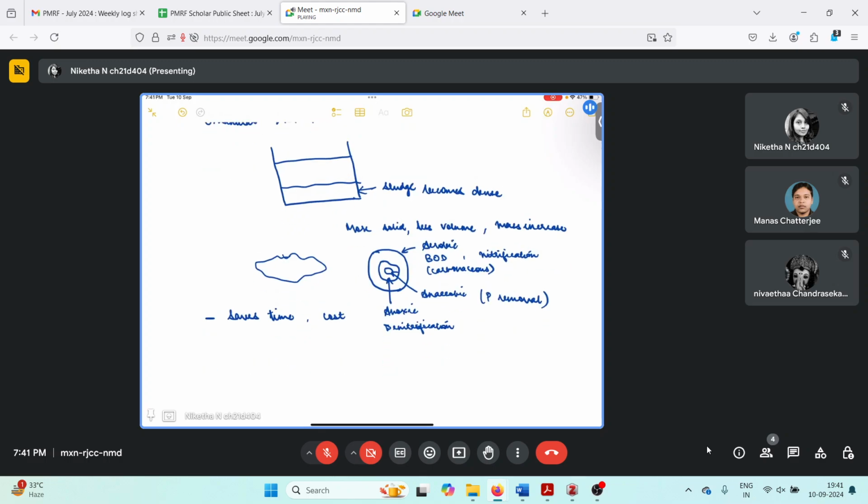So instead of having regular sludge, which is like a huge mass of watery substance, we are going to have granules of sludge, which is also made of the same bacteria, but it is densely packed, and that is why the innermost layer will not have any oxygen. The outer layer will have a lot of interaction with the air, and that is going to be aerobic.